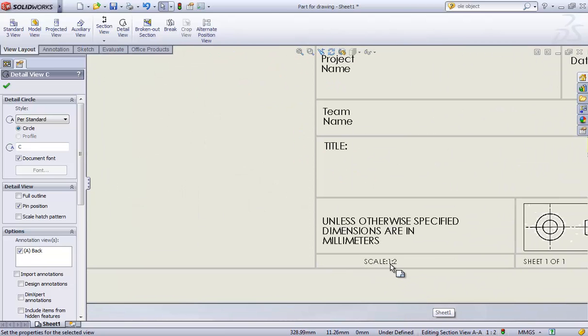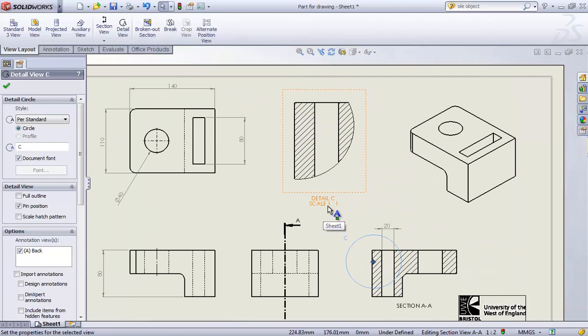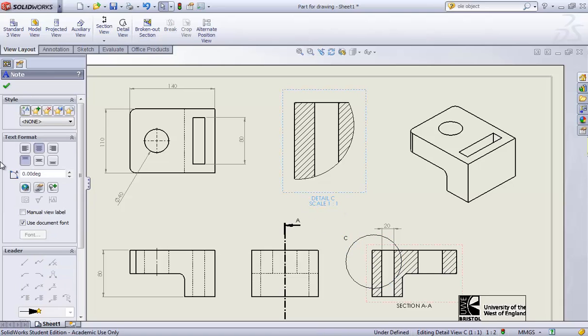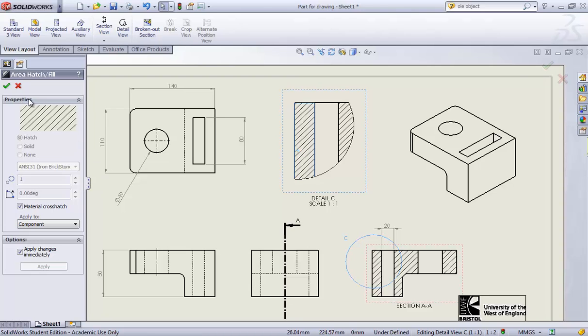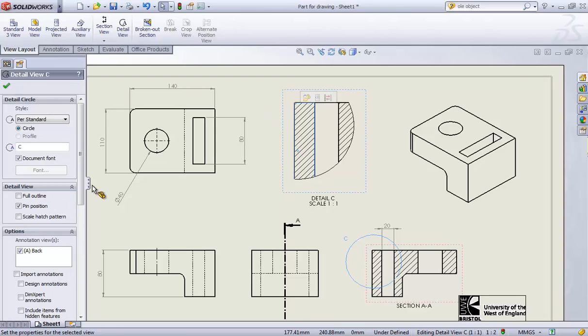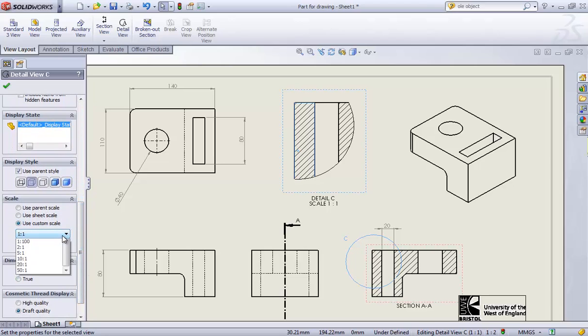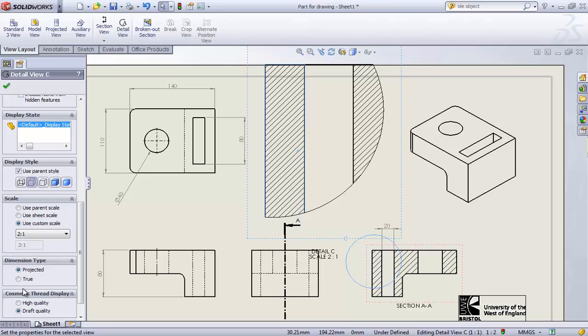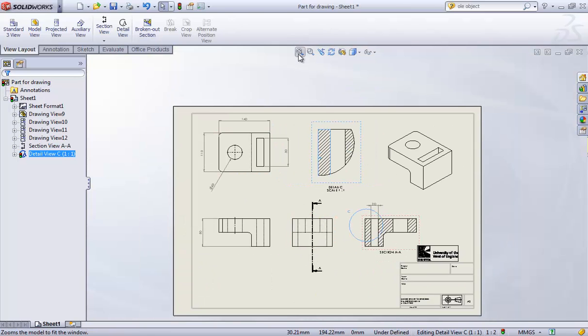Right, the overall scale for this document is 1:2, but you wanted to show the details for this one, which is at higher scale. If you wanted, you can always change the scale of this view here by, I don't want to select that, I want to select the view, and I hope over here somewhere we have the option, so you can go double the size, 1:1 scale. So that's how you create the detail view.